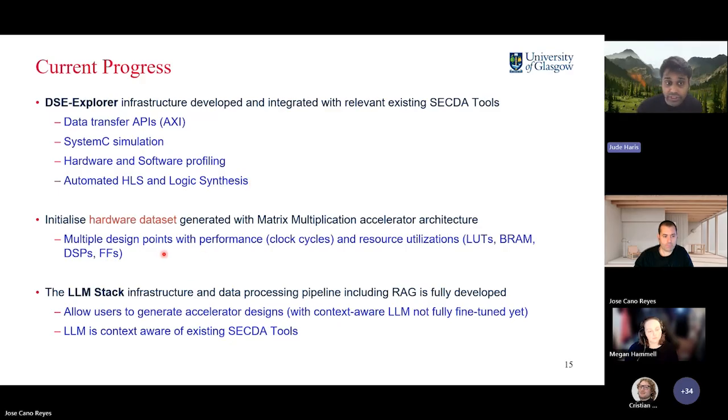Additionally, using this DSE Explorer, we have already generated an initial data set with a matrix multiplication accelerator architecture. This data set contains multiple design points with performance metrics such as clock cycles and also hardware utilization metrics such as LUTs, block RAM usage, DSPs, flip-flops, and such, which are common metrics for FPGA-based designs.